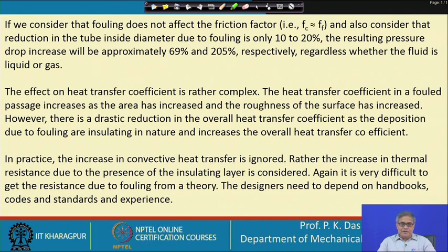That is one part, and the second part is that we have seen in the photographs that deposition of foulants makes the surface irregular, and generally this irregularity gives an increase in heat transfer coefficient. So, the heat transfer coefficient will increase by these two effects.